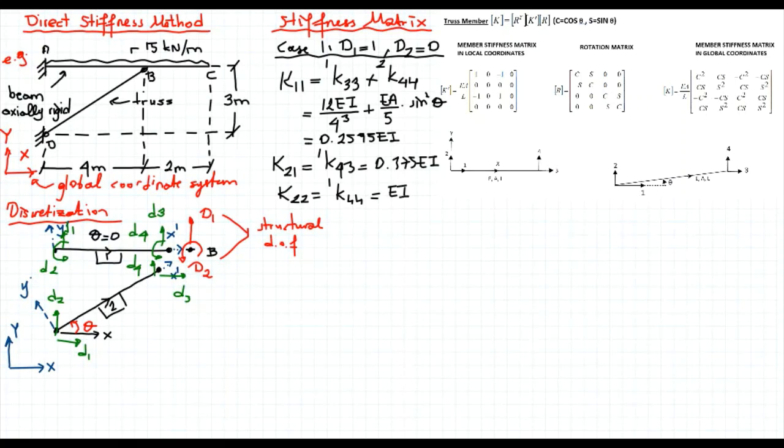So as you see, we obtain the same stiffness matrix. The only difference is I didn't give a unit translation in the vertical direction to this truss member and try to calculate how much axial force I have on it. I did it once in this case, and I just directly used it.